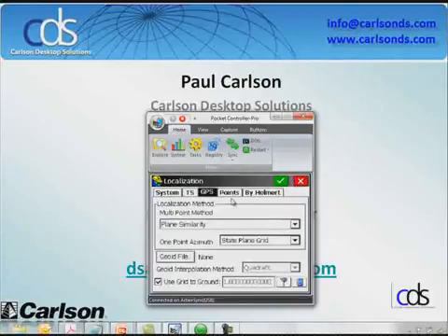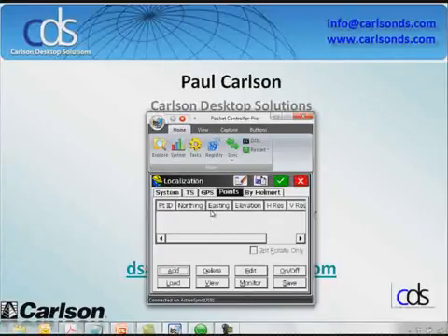So my scale factors, and then my points, this is where I actually do my localization. This is really no different from what we've always seen. I would go in and add my point number, take my number of readings, and then I can turn the positions on or off, turning on horizontal location or vertical. So I could have 15 localization points. 5 of these I want to use for horizontal, and 5 of them I want to use for vertical. Okay, so I can turn things on and off as I need. No real difference there.